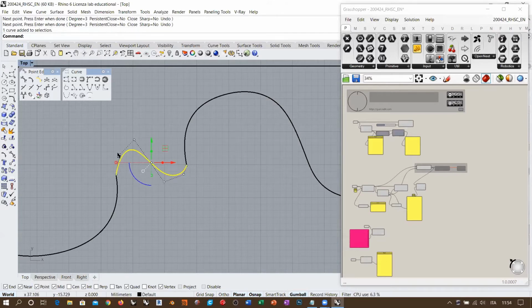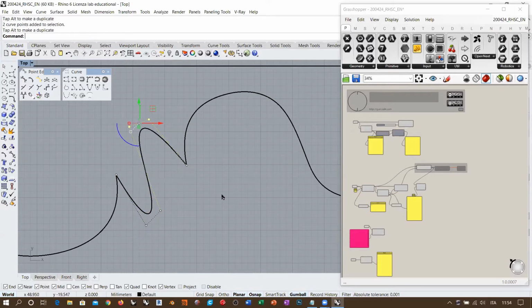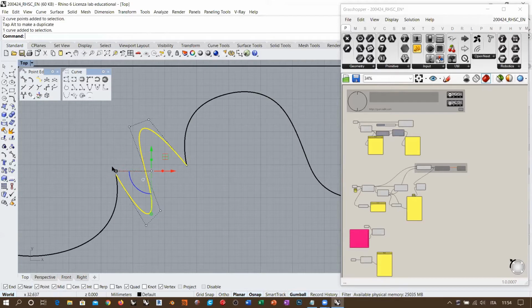By drawing this, no matter where I place the other control point, it's absolutely irrelevant, okay? But I have the right topological structure in order for Rhino to edit the shape of this curve and create curvature continuity in this connection point and in this connection point. We will be discussing this later when we will deal exactly with the continuity.